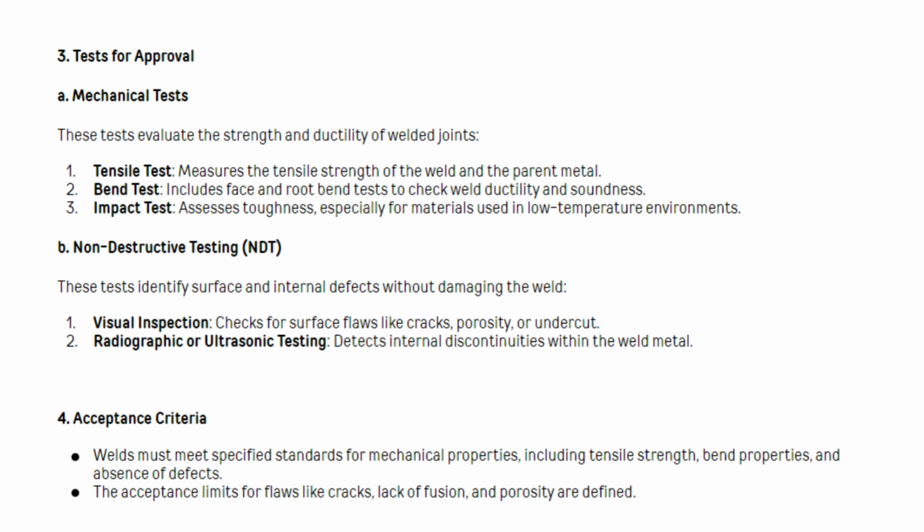B. Non-destructive testing, NDT. These tests identify surface and internal defects without damaging the weld. 1. Visual inspection checks for surface flaws like cracks, porosity, or undercut. 2. Radiographic or ultrasonic testing detects internal discontinuities within the weld metal.